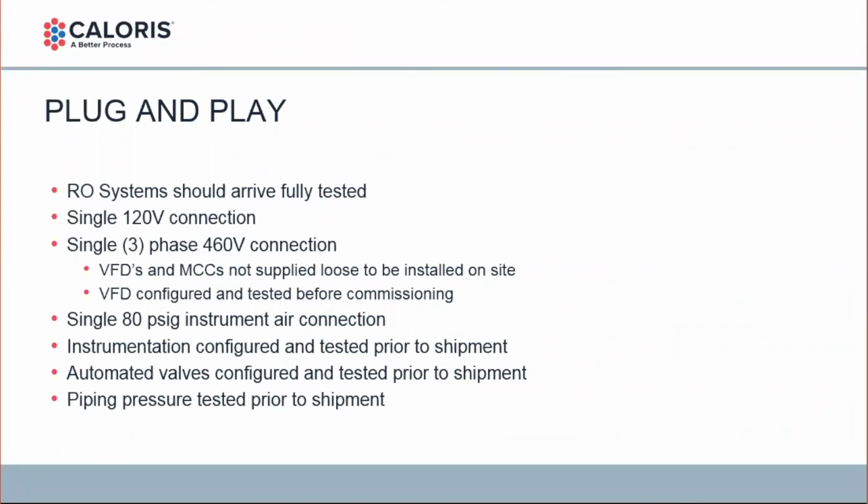The VFDs and MCCs should not be supplied loose. The VFD should be configured and tested before commissioning. You should have a single 80 PSIG instrument air connection. The instrumentation should be configured and tested prior to shipment. Automated valves should be configured and tested prior to shipment, and you should have the piping pressure tested prior to shipment.